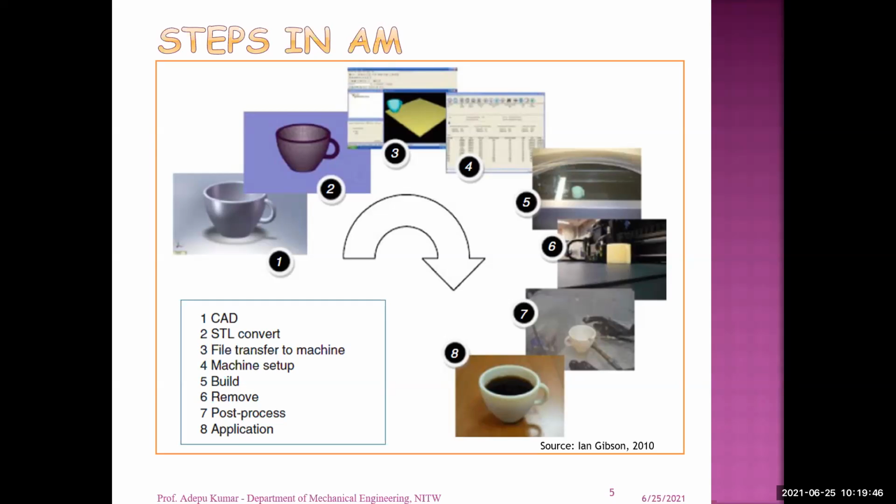But in a microscopic view, a plate is also considered to be a 3D object. Even though the thickness is very small, microscopically we can call it 3D, sorry. Similarly, the STL file is the combination of all triangular facets, which leads to a 2D object with minimal thickness. Each layer has its own geometry, or the same geometry, or a different geometry. It doesn't matter. Irrespective of the geometry on each layer, the machine can understand it from the STL file.